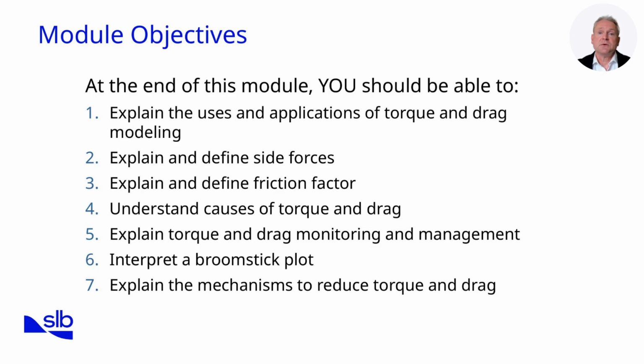Second, interpret broomstick plots, which compare measured loads to modelled values. These plots are powerful diagnostic tools, allowing us to identify poor hole cleaning, cuttings bed development, or excessive drag during casing runs. Third, evaluate how drill string design influences torque and drag.